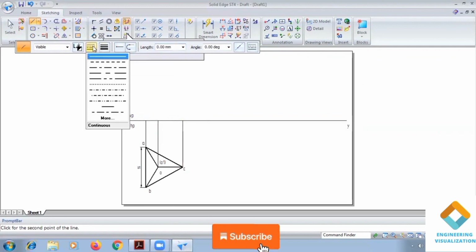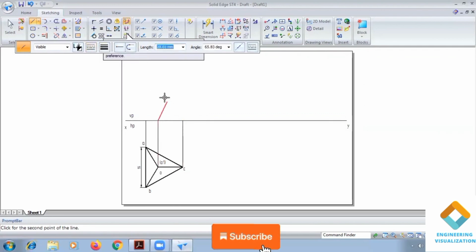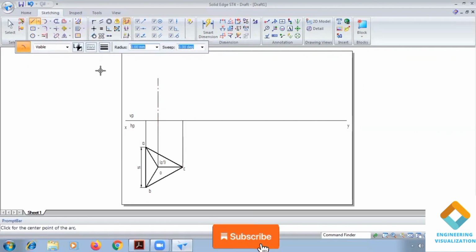Okay, in this tetrahedron problem we don't know the axis length. Just randomly draw it, and from one end, which is parallel to x, you can see why it is parallel. That's why we are cutting the arc from this end with a length of 55 mm radius. Cut the arc. Okay, now join it.